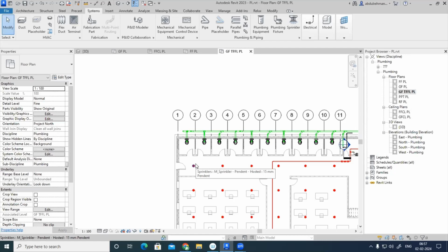On the ground level, I'll be taking the drain connection or the waste connection through the raised floor only. On the first floor, I'll be taking it between the ground floor ceiling level and the first floor. When making these kinds of drawings, we normally call them the ground floor low level drawing and the ground floor high level drawing. So through the ground floor high level only, the first floor connections will come.